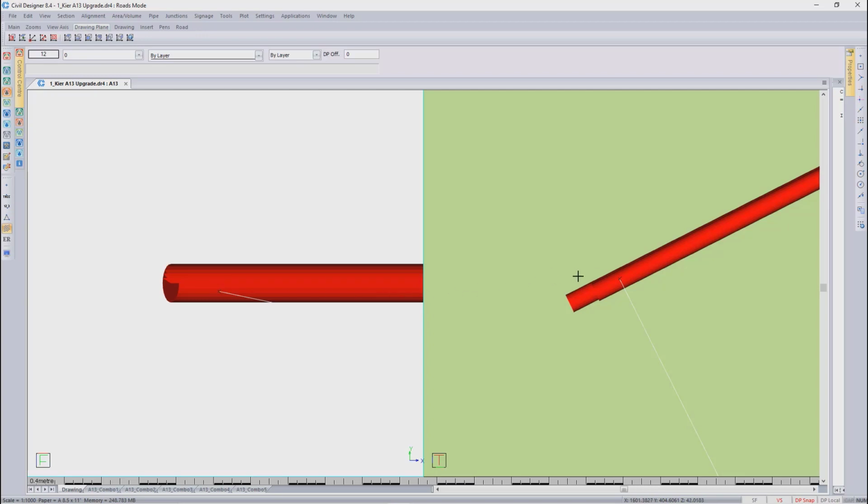If you look at the top view, you can see X indicating my last fixed point. If I select the top view and make that active, again make that the current view, press X, there I can obtain my XY coordinates.